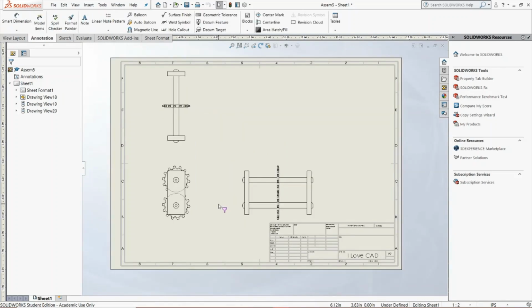Okay, and we're back. As you can see, I have removed our previous views and I've implemented these views as well. Furthermore, you'll also notice this pink funnel filter looking icon right by my mouse, and this is a very pesky thing to work with. It's essentially a selection filter that only allows you to select, in this case, vertices or faces even. So to get rid of that, you just press F6. So Fn, F6, F6. There we go. And it's gone. My apologies for that. It wasn't working for a moment there.